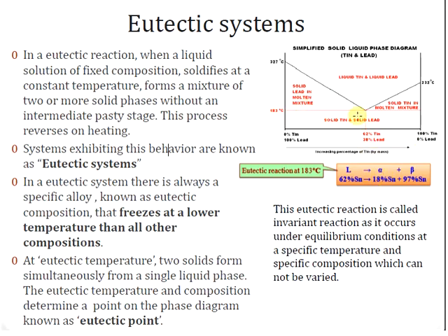At this point alpha corresponds to the solid lead point, that is 18 weight percentage of tin, and beta corresponds to 97 weight percentage of tin. You will understand these values from the next slide, because this diagram is oversimplified and does not show the alpha and the alpha plus beta separations.